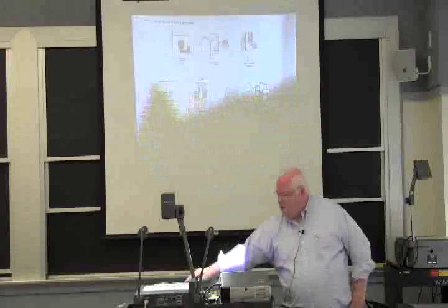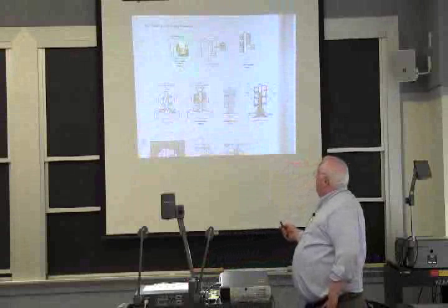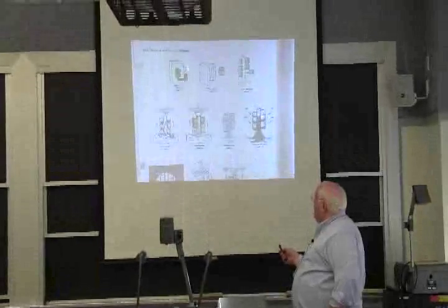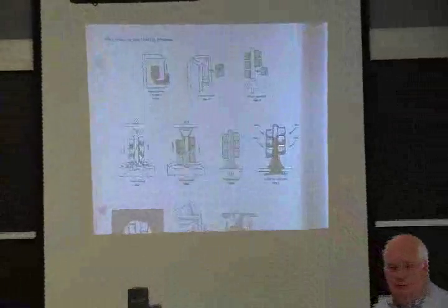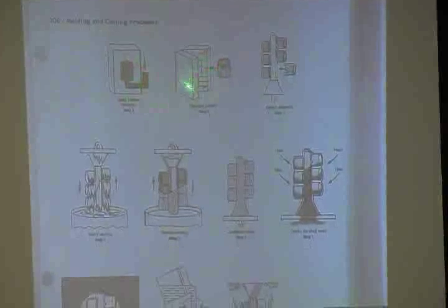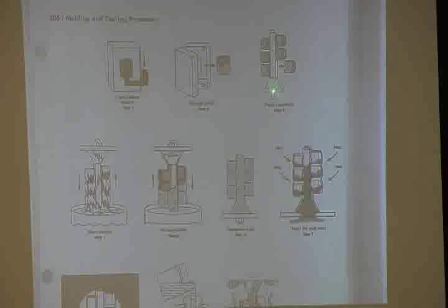Lost wax casting, essentially you make a wax part. Today, we have a permanent mold which you can machine into some complex shape, and you inject wax in there. So you can do all this at less than 200 degrees Fahrenheit. You pop the wax part out of the mold. You now take some wax rods and you put these little wax parts together and weld them to the other wax.